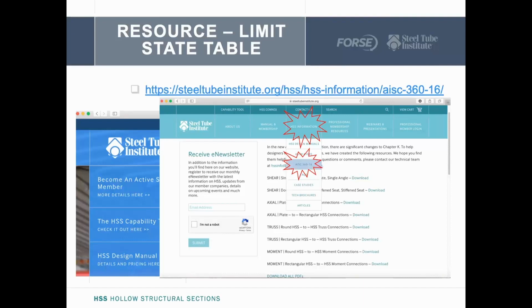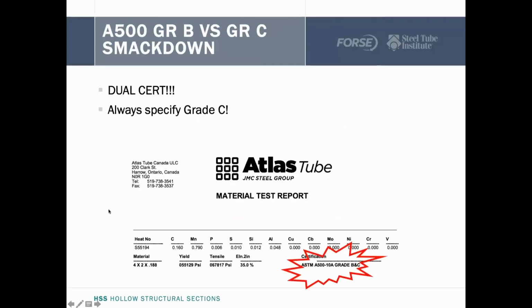All right. Last thing I wanted to talk about real quickly is the A500 B versus C. I know this is a little bit off topic, but those of you that have gotten into the new specification hopefully have noticed that all of your column tables are based off of A500 grade C. Our producers are very smart people. They don't stock 2 sets of coil. We've been receiving dual grade material for at least 10 to 15 years, and we haven't known it. So we need to go ahead and be specifying A500 grade C for our designs, because that's what we're getting, that's what we're paying for. You're not going to be asked to pay a premium for that.